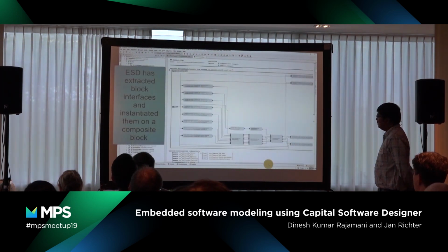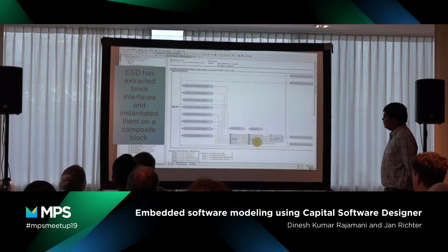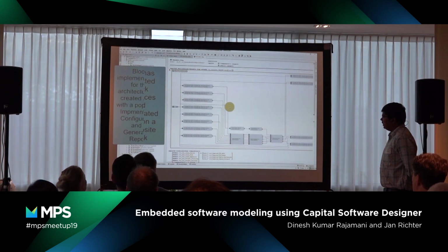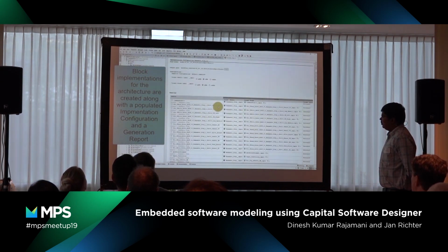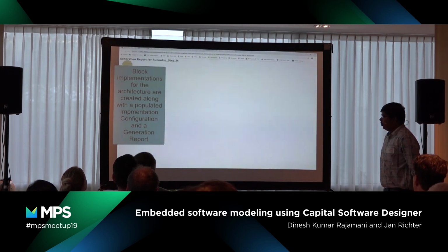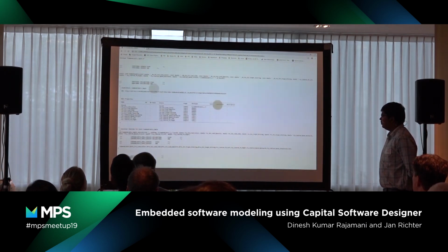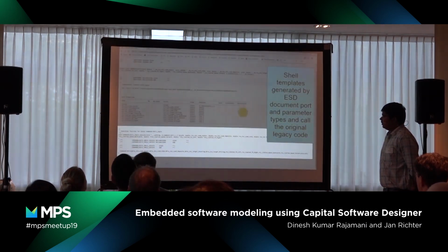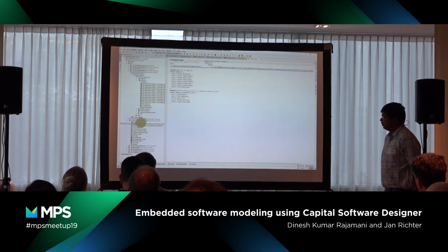The complete function call graph has been transferred into block diagrams, into data flow. This is externally referring to the original C code. This is an implementation configuration which maps what is being imported, and we also show some reports with proper comments on what is called in the original C code.